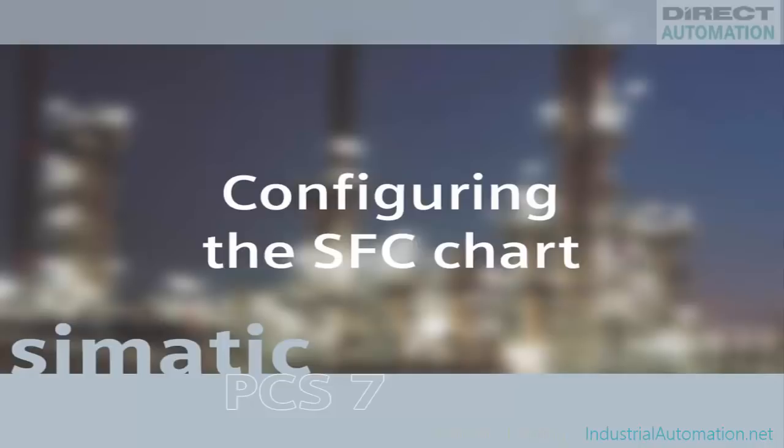Before the CFC charts are interconnected, an SFC chart must be created to control the sequential operation of the motor and valve, since this configuration logic must also be available for the second plant section.